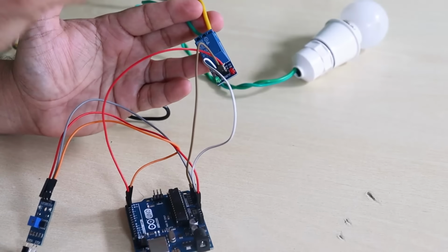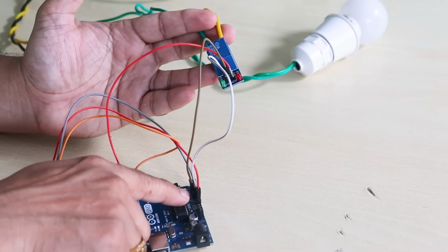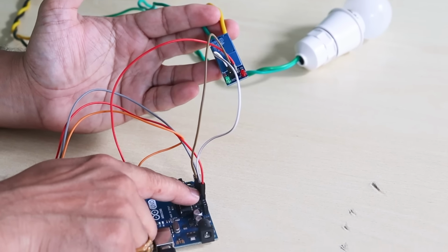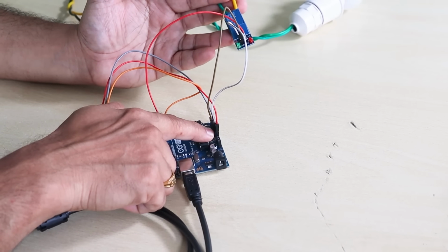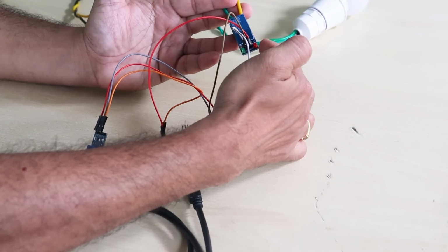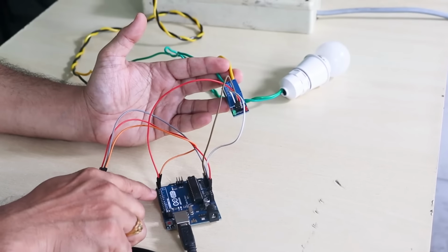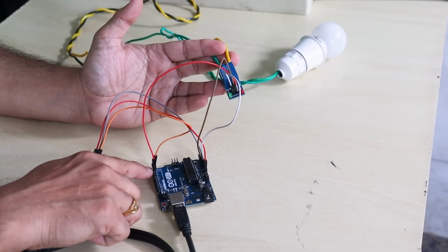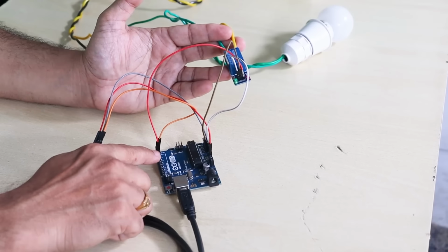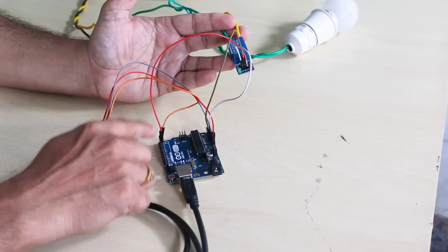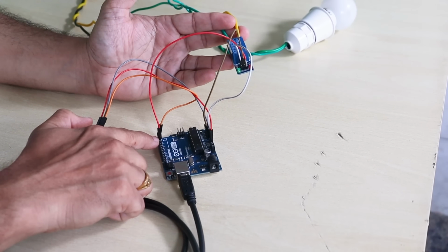Since the relay takes 5 volts as the input, we have to give VCC to the 5 volts of the Arduino board. The other pin, ground pin, is given to the common ground of the Arduino board. The remaining third pin, the last pin, is given as input pin, which is being given at pin number 4 of the Arduino board. So this VIN is actually the command sent from the Arduino to control this relay, that is being done at pin number 4 of the Arduino.